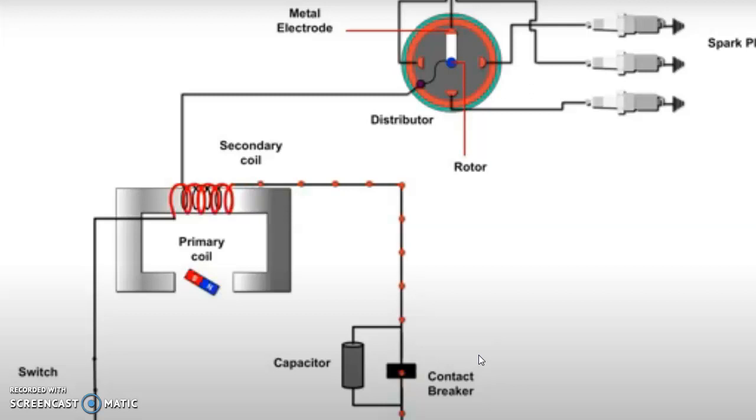Now the high voltage EMF produces a spark at the specific spark plug through the distributor. As the engine speed is low at starting, the current generated by the magneto is quite small. As the engine speed increases, the flow of current also increases. Thus, with the magneto ignition system there is always a starting problem, and sometimes a separate battery is needed for starting.